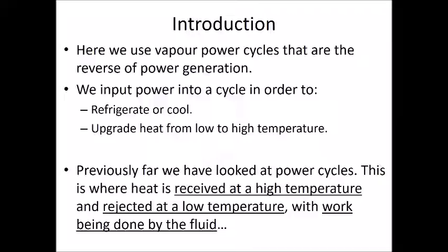So first of all, we have to remind ourselves that this is the reverse of power generation. So we take work and we turn it into heat, or we move heat using work, not the other way around, as I've said previously. So we put power into a cycle to pump heat from one location to another. And in the example you've just seen in the refrigerator, we pump heat from the inside of the fridge or the freezer to the outside. And it's not really relevant which is the high and low temperature reservoir.